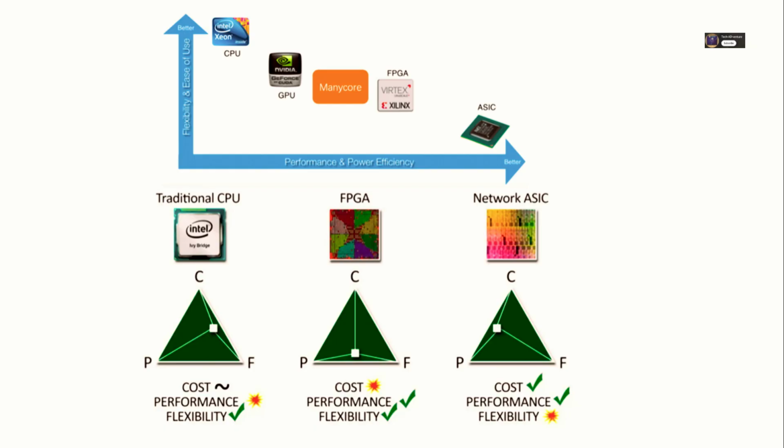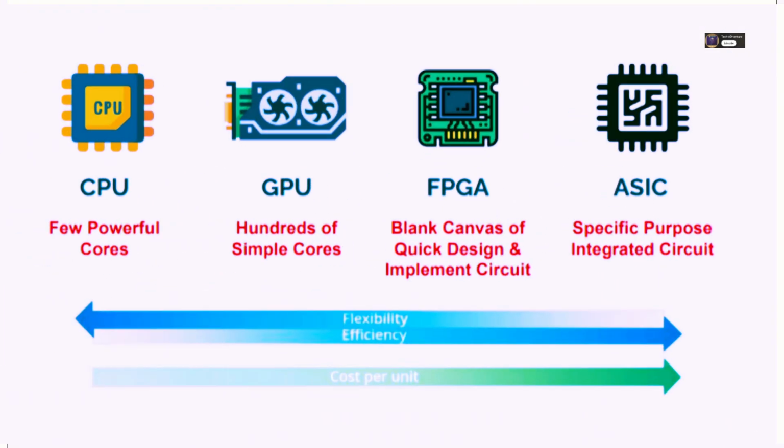Right. Designing an ASIC, getting the mask made, fabricating it, that costs millions of dollars up front. And the design cycle is long, easily a year, maybe two. So if you only plan to sell, say, 10,000 units of your product, that NRE cost spread over just 10,000 units makes each chip incredibly expensive. Prohibitively expensive usually. The FPGA, while maybe more expensive per chip initially than an ASIC could be at volume, has virtually zero NRE. You just buy the FPGA and program it.